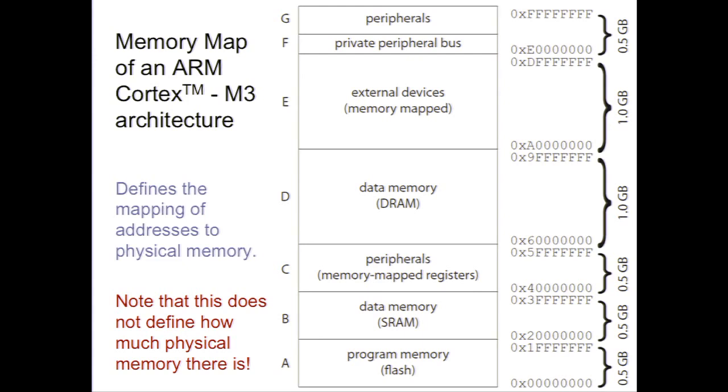It's probably going to get zeros always, maybe, if the circuitry is designed that way. If you read from an address where there's no physical memory, a carefully designed circuit would probably give you at least a predictable value, maybe just all zeros. But it's certainly not going to be the value you wrote to that memory location. Now, you don't see this problem when you write programs on your laptop, because the operating system and the compiler together make sure you never write to physical locations that don't exist. But when you're writing a C program for a bare iron processor, you can write to any one of these addresses, and the hardware will just do what you told it to do. Hardware is stupid. It does what you tell it to, and if you tell it to do something stupid, it'll do something stupid quite happily. So you kind of have to know how this is going to map into physical space.